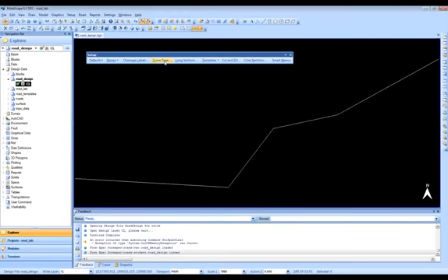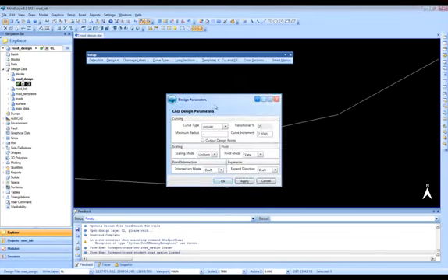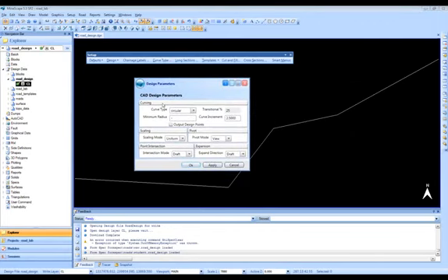Another area of setup is curve type. Under the curve type, you can set up what type of curving you want to have here on your road design. You can choose a circular curve, but you could also have a transitional curve. A transitional curve will basically put a spiral curve from the point of tangent to the point of the curve, and then around the curve, and then you spiral back out. It just gives you a smoother road design curve calculation.